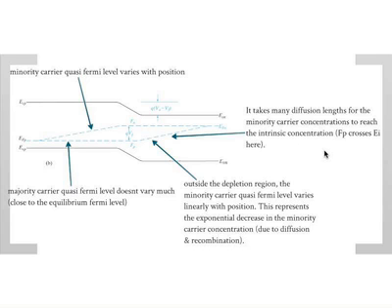It reaches the intrinsic concentration, F_P crosses E_i. Oh, sorry, the other thing to think about is you have an intrinsic band energy level, which is roughly halfway in between the band gap, right? So you can also calculate at what position the excess carrier concentration, or the total minority carrier concentration, will reach the intrinsic level. This is a little bit of a subtle point.